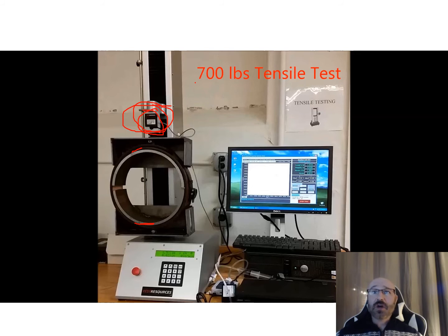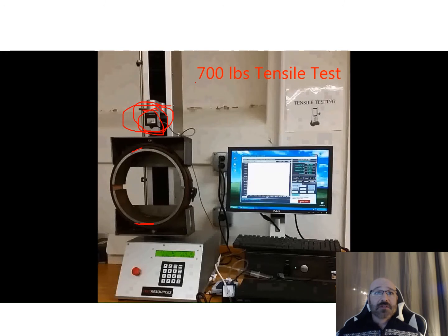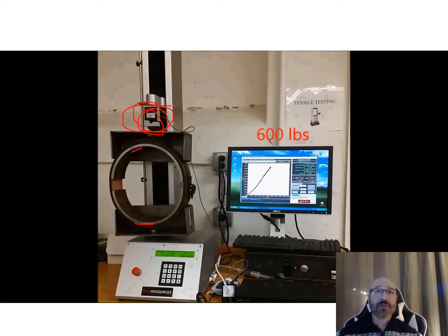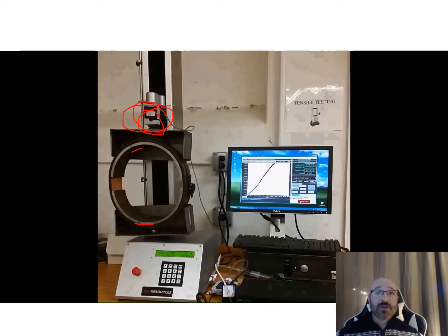So I'll play the video for this now. We can see, when I sped this up, you can see this expanding right there. You can see that crack moving up and up. You can watch our force versus displacement curve live right here: 400, 500, 600, 700 pounds, and still staying pretty linear and continuing to rise.